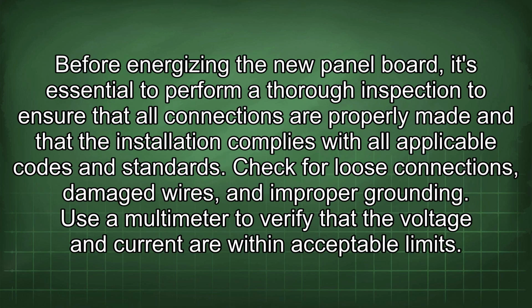Before energizing the new panel board, it's essential to perform a thorough inspection to ensure that all connections are properly made and that the installation complies with all applicable codes and standards. Check for loose connections, damaged wires, and improper grounding. Use a multimeter to verify that the voltage and current are within acceptable limits.